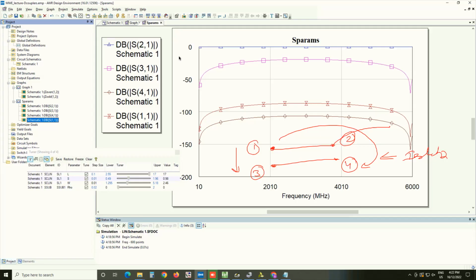That power goes to port 2, and there is some device there whose reflection coefficient you're trying to measure. That signal will bounce off and come back through port 2. That power coming into port 2 is coupled 1% into port 4. So port 4 can become a measure of the reflected power, right?